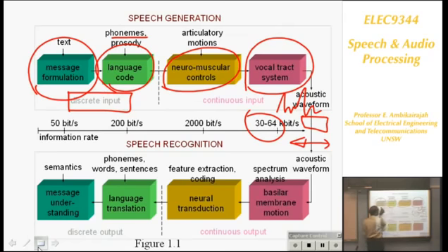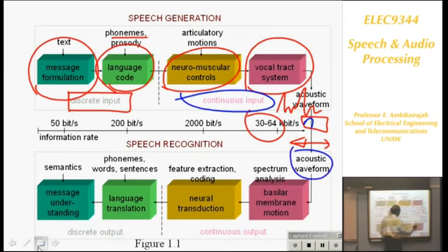So these are all discrete, and then you move into analog because these are all moving continuously, and what's coming out is analog, but you want to use a computer to process it. That means you need to use an A to D converter here to convert this analog waveform into a discrete waveform.